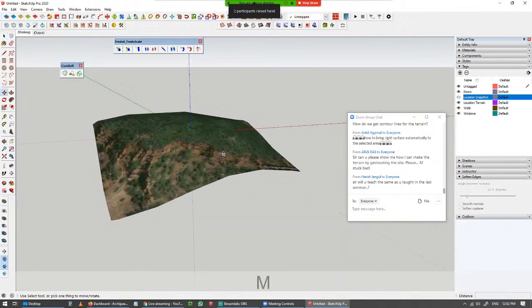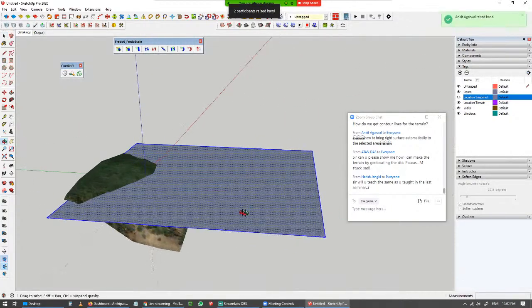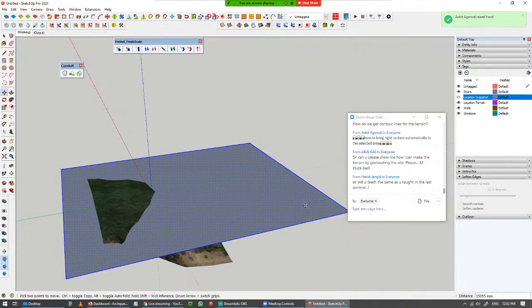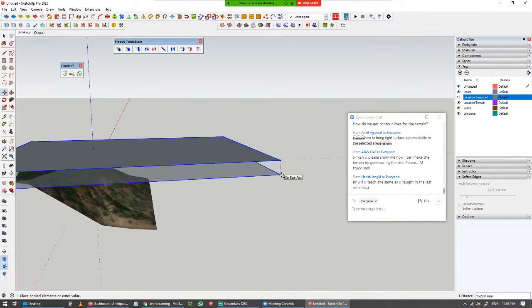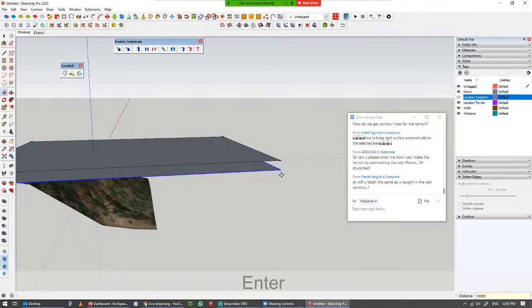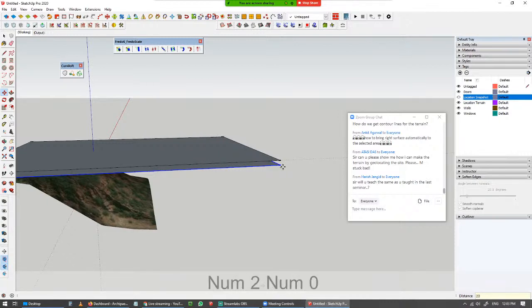Okay. Now I can create intersect rectangles which can be used to intersect with this particular terrain. I have demonstrated this in my previous workshops, but let me show it once again. I'm going to give it a spacing of 10 meters. In fact, the contour interval, in this case I am assuming to be 5 meters. Enter, and I'm going to repeat this, say, 20 times.